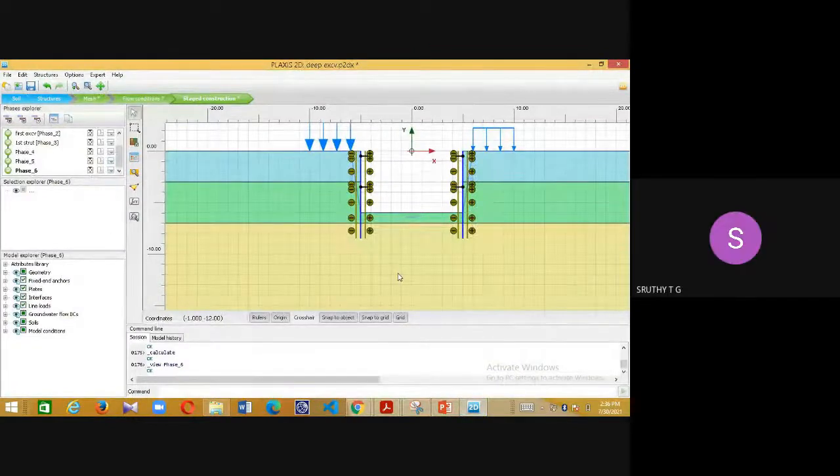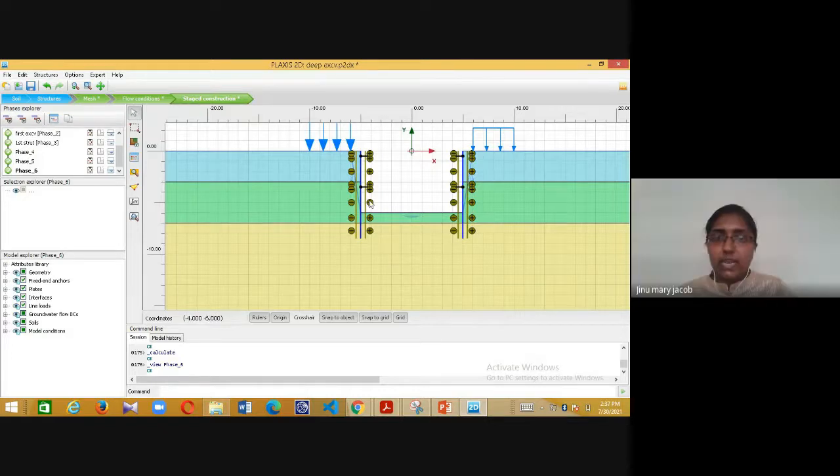Okay. So what is the maximum extent, the maximum slope that can be provided in the dewatering condition? It is preferable to go for a conservative design. So we usually take 0.5 meters away itself. But in actual site conditions, we may have a dewatering point at some 1 meter or 1.5 meters away. So the actual drop point may be even farther. So to be more conservative, it can be taken at 0.5 meters away from the wall. Okay, ma'am.